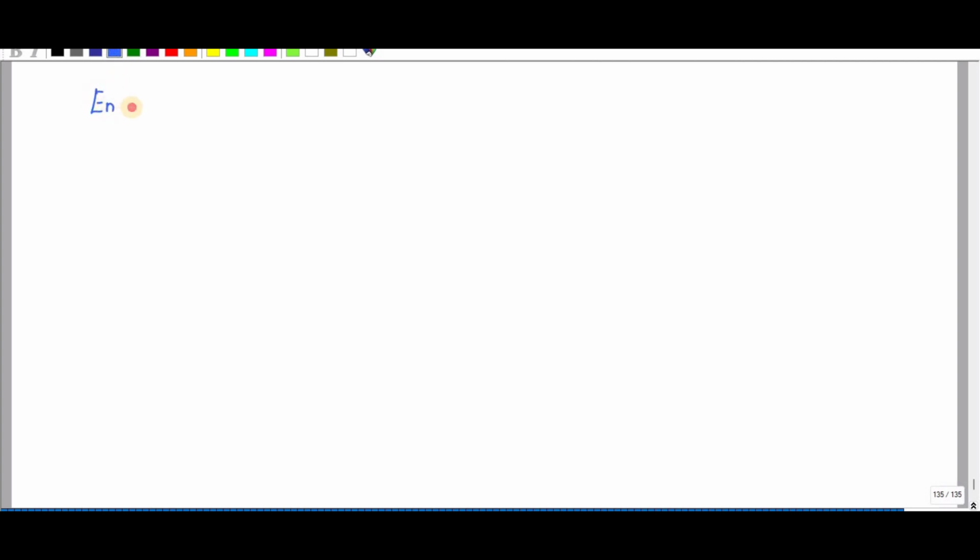So in this video we are going to discuss the encoder. Here you have the formula 2 power n to n. Let me consider the n value is equal to 2. If n is equal to 2, you will get a 4 cross 2 encoder. 4 is your input and 2 is your output. Let me term the inputs as I3, I2, I1 and I0, and y1 y0 is your output.